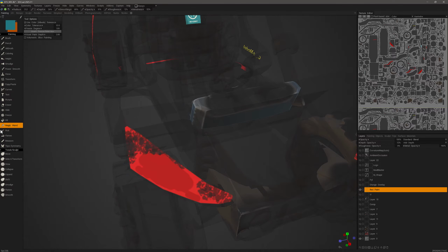I can essentially invoke the pick tool by hovering over the area that I want to sample from and hitting the V key. You can do this with depth, color, and glossiness. So I'll disable depth and glossiness and just use color for now because that's really all I'm interested in. So let's go ahead now and pick that area. You can add to the selection by holding down the Shift key.